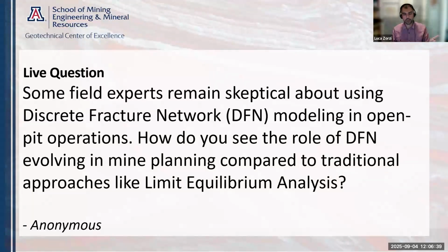Where you have a good amount of data that would allow you to go down the path of a discrete fracture network, that would be advisable, because in that case you're building more realism into your modeling. When you don't have enough information, then you shouldn't even consider DFN, because you can go down the path of something that is not usable or not realistic at all. So, know what you're doing, have the correct amount of information, a robust structural model, enough information that you can build a DFN. So not only your fracture frequency, but also your continuity.